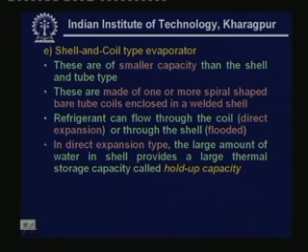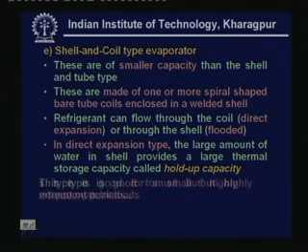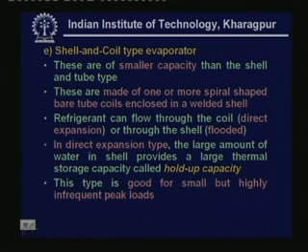In direct expansion type, the large amount of water in shell provides what is known as a hold up capacity. That means a large thermal storage capacity is provided by the amount of water in the shell, and this is known as hold up capacity. And this type is good for small but highly infrequent peak loads.